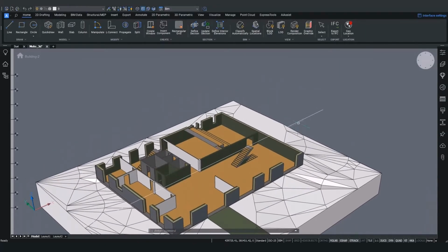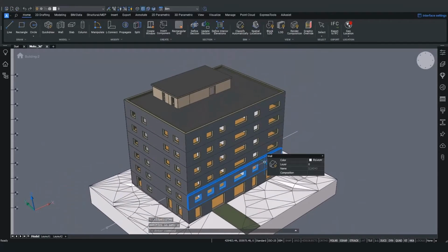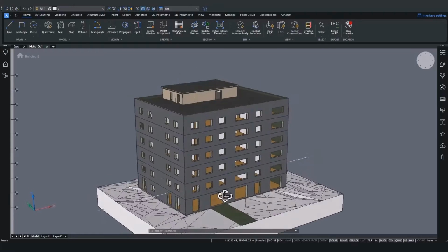Also note that when importing only a subset of BIM classifications, the importing mechanism will exclude upfront all these BIM categories you don't need to import, speeding up your import, because in this case, windows and doors were not included in the import. You can now start to model with these elements just like native BricsCAD elements.